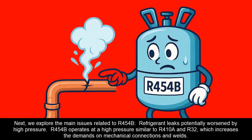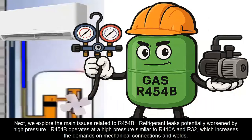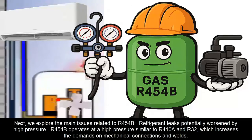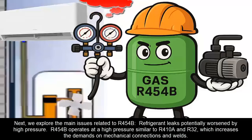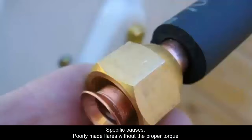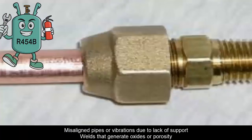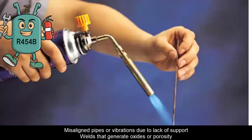Refrigerant leaks potentially worsened by high pressure. R454B operates at a high pressure similar to R410A and R32, which increases the demands on mechanical connections and welds. Specific causes: poorly made flares without the proper torque, misaligned pipes or vibrations due to lack of support, welds that generate oxides or porosity.